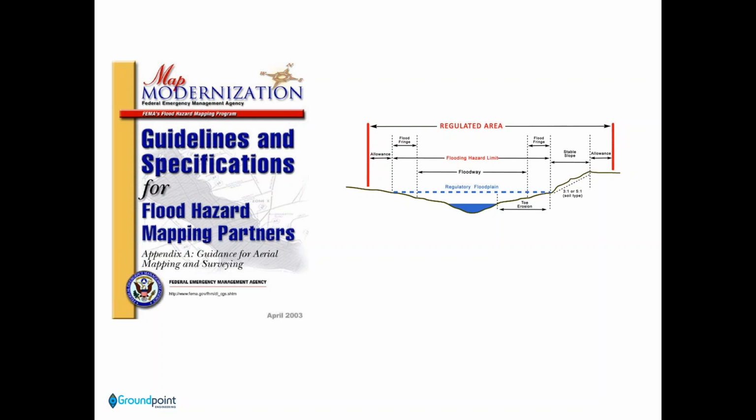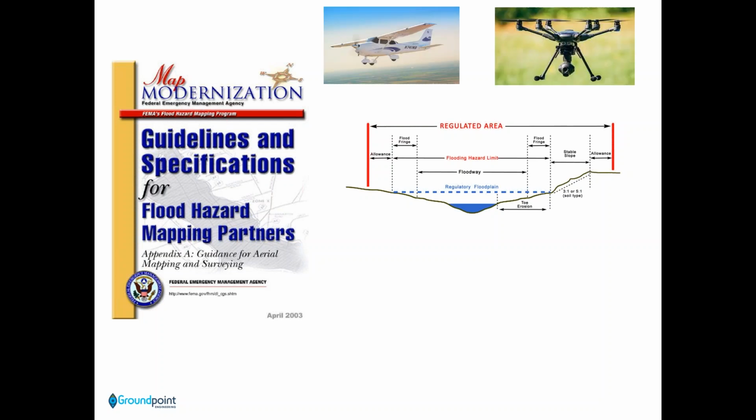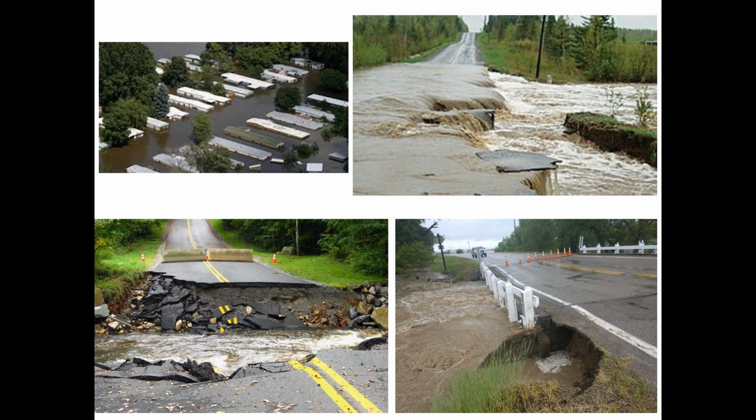So fast forward to now, and the data is getting better. We have drones now that give us ridiculous detail. LiDAR data is ubiquitous. Local LiDAR updates have higher resolution, more points, and more detail. So now we want to be able to use that data to start looking outside the floodplain at the landscape that's actually contributing runoff.